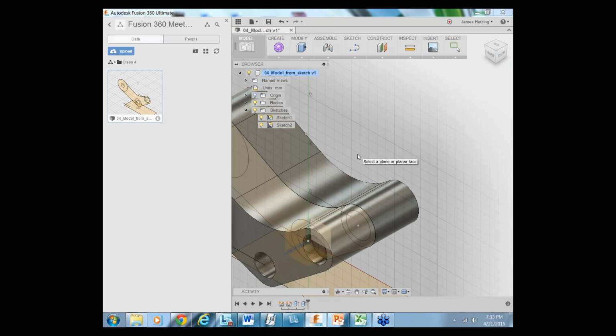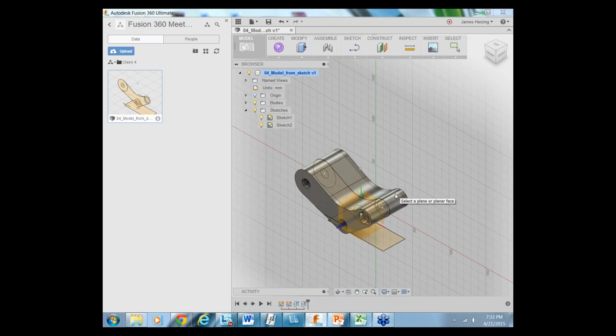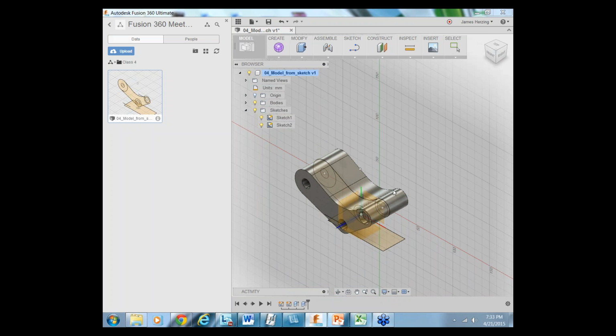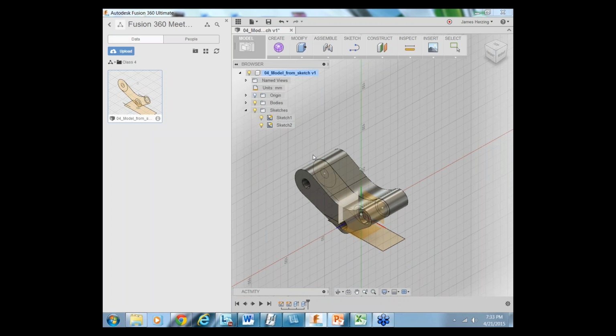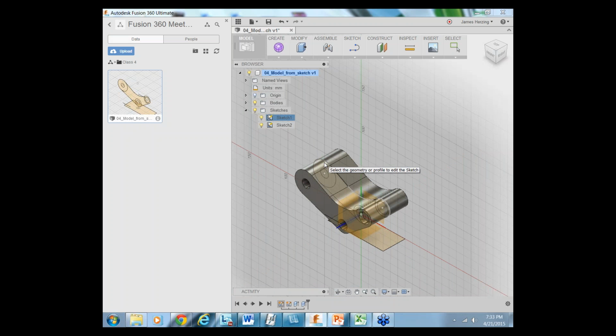So what are we going to do? Click on the outermost surface of your cylinder. So this is going to be a little bit tricky, I think, for some of you. You can see that as I move my mouse around, I'm hovering or highlighting different planes. Right now, you can kind of see on my screen that the plane that I would be clicking on would be the midpoint of my part, so that original plane that I was working on.